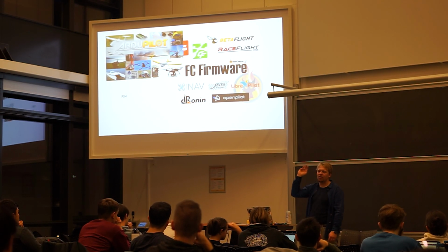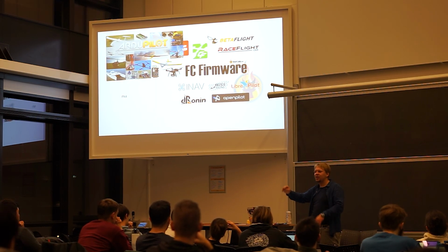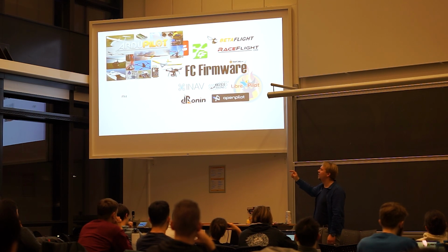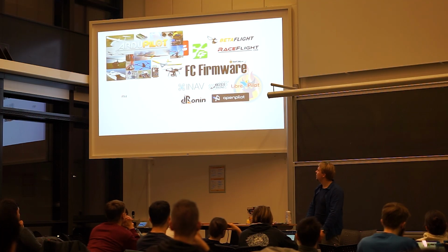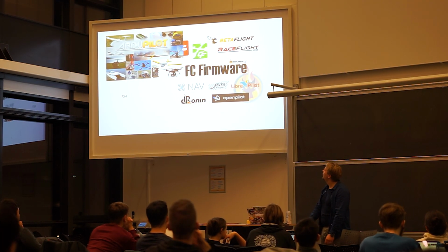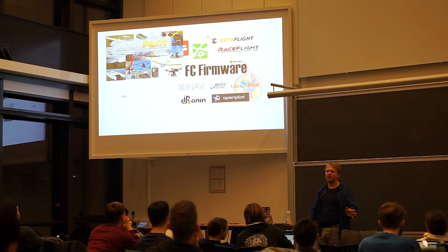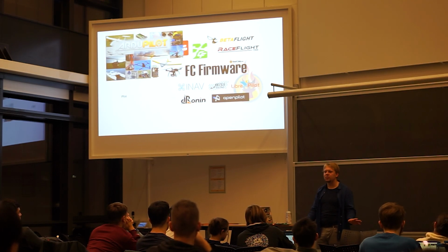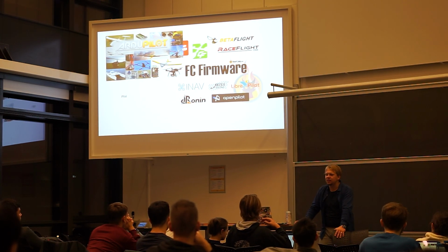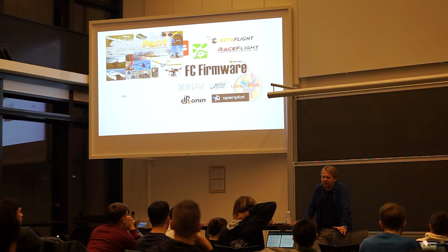And if you need any automation, if you want to learn for yourself, you could go the route of INAV first and then Ardupilot, but just skip the INAV part. There's no reason not to just go to Ardupilot or PX4 and learn that. So Betaflight, Ardupilot, PX4, that's the main stuff. Betaflight is the most bare-bones, like Arch Linux. It runs really fast, does good filtering, and doesn't have any extra features.